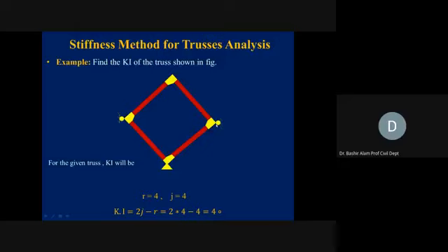From the right one, it can move in the vertical direction, so 1 degree of freedom from here. And from the left, again, it can move in the vertical direction, so 1 from here also. The bottom one is not allowing any kind of displacement. So it means it is a 4 degrees indeterminate problem. This was the kinematic indeterminacy by observation.